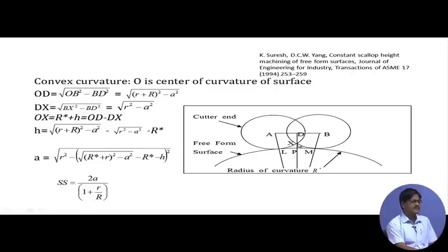What we can say is that here there will be one right angle triangle x d b. So, we can say x b, which is nothing but the radius of the cutter, squared must be equal to x d squared plus d b squared. D b happens to be half the center distance. So, we can introduce center distance into the calculation with cutter radius and this particular distance x d.